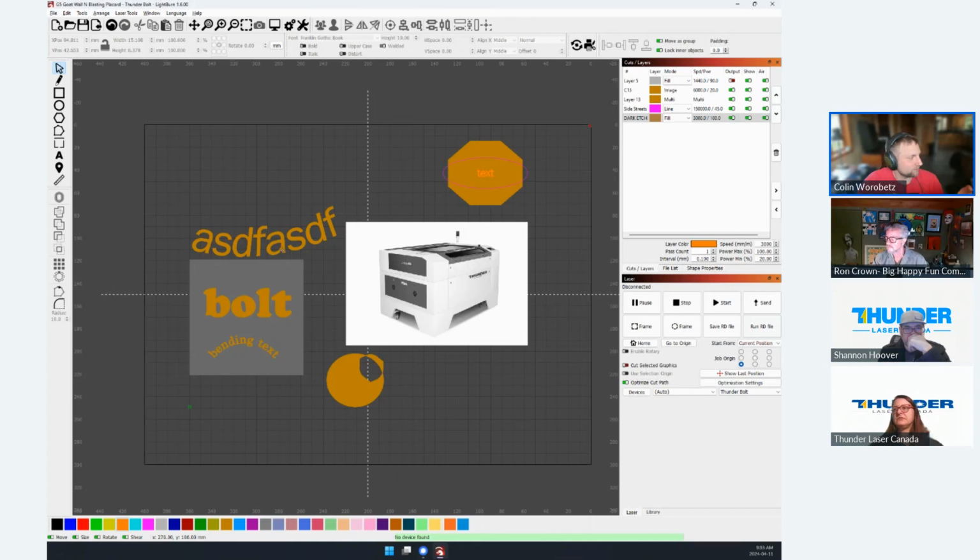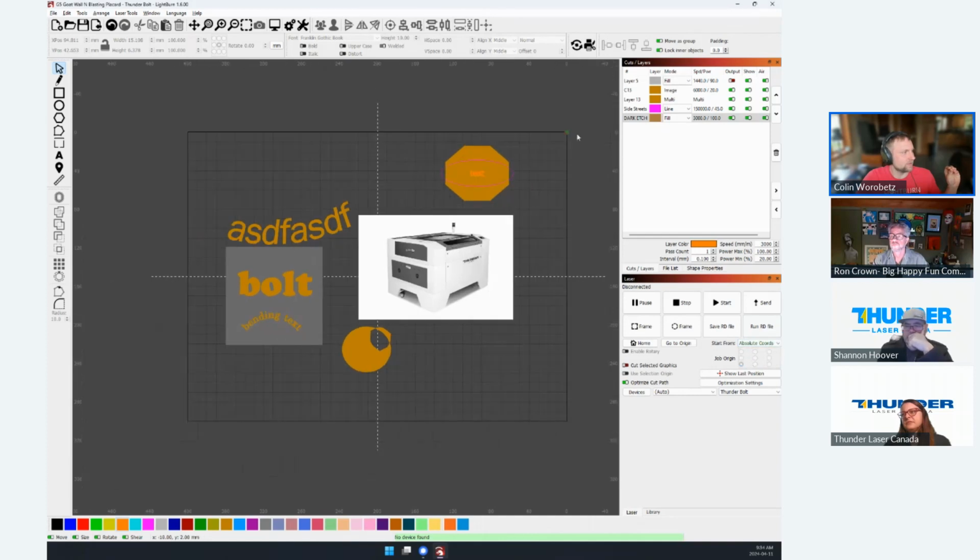Yeah. So the most important green dot on the screen is this little one here. And that shows where LightBurn assumes your laser head to be if you're not using absolute coordinates. So with absolute coordinates, you can see the green dots move to the top right of the screen. And so that's where everything in LightBurn is done from. It assumes we're going to work from that point. If you change to, say, user origin or current position, the current position and user origin are the same right now because I haven't set a custom user origin on the control or in LightBurn. But this green dot is now where it presumes everything to be. So you're going to want to have your laser head there, and then it's going to work up from that point.